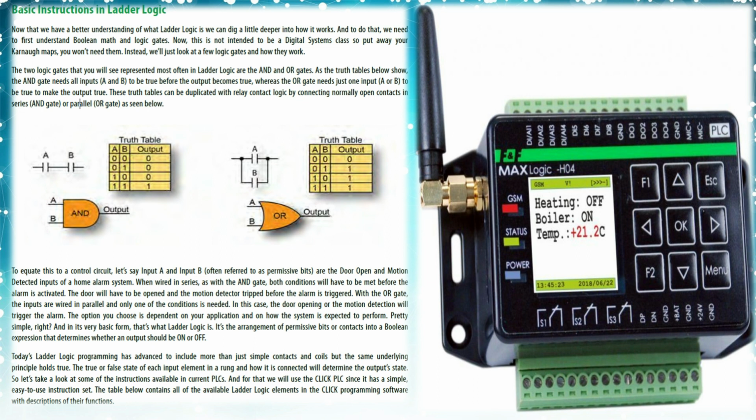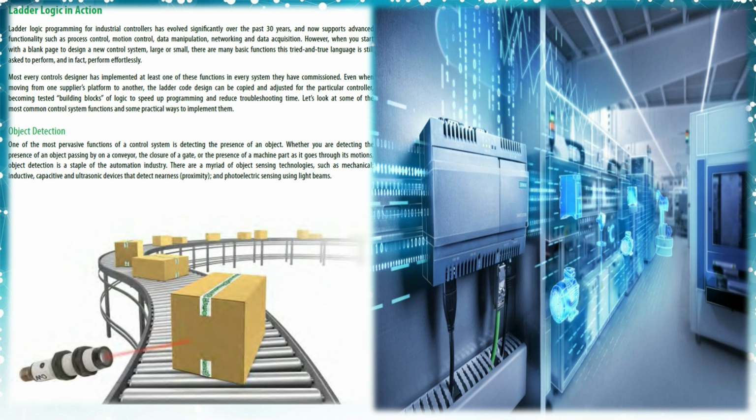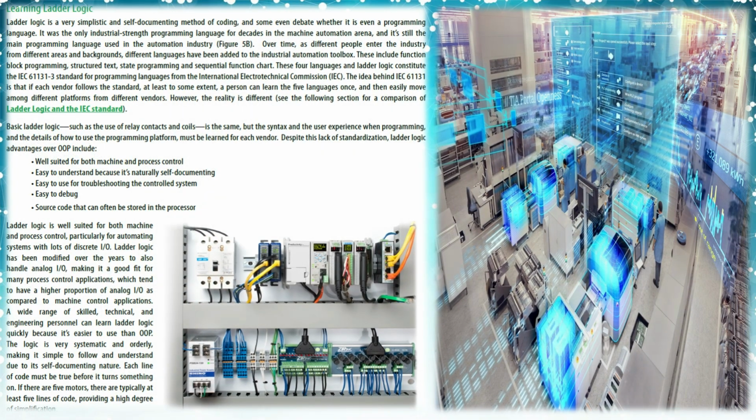Input and output module. Have you ever thought about how to sense physical parameters like temperature, pressure, flow, etc.? PLC has an exclusive module for interfacing inputs and outputs, which is called an input and output module. Input devices can be start and stop push buttons, switches, etc., and output devices can be electric heaters, valves, relays, etc. Input-output module helps to interface input and output devices with a microprocessor.